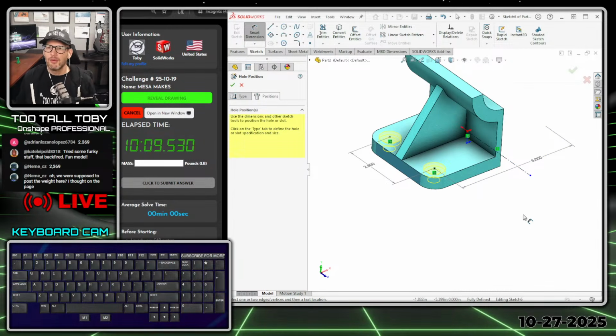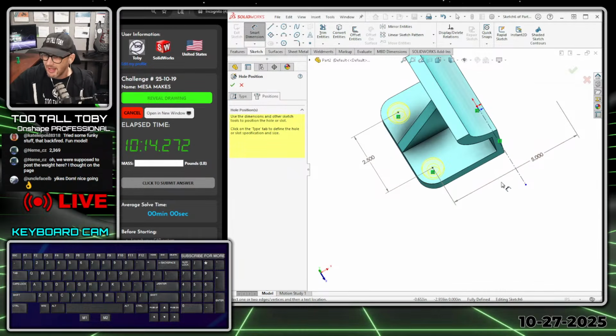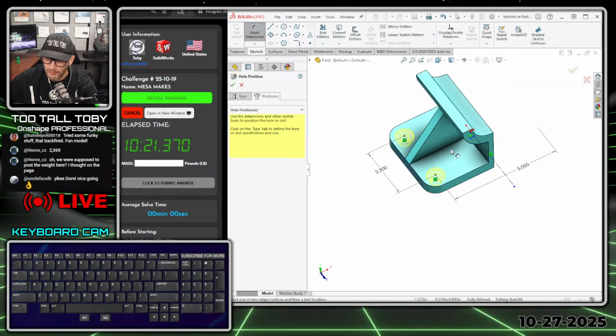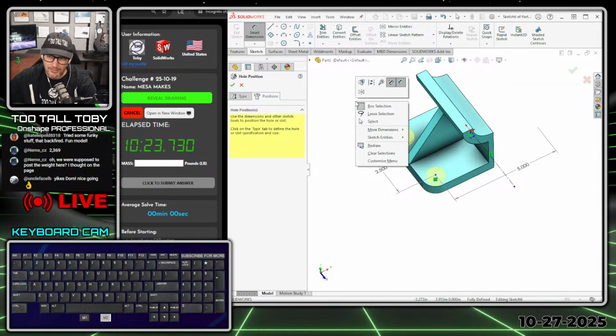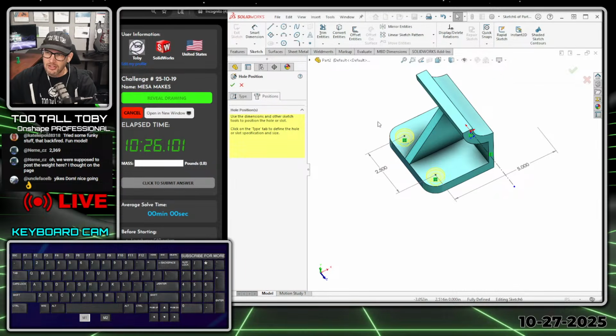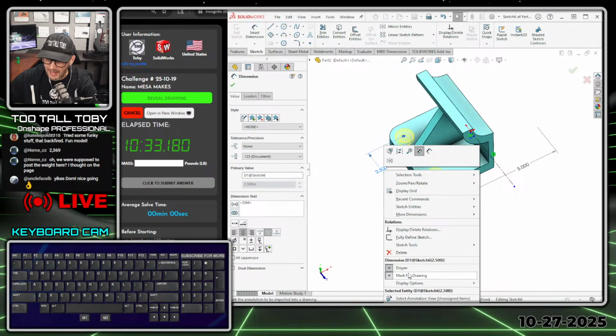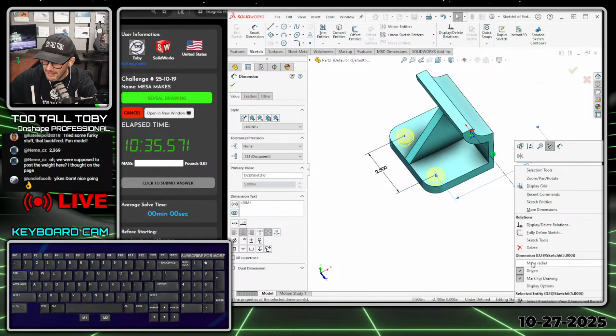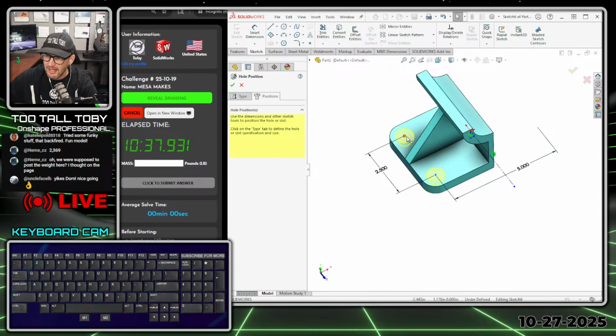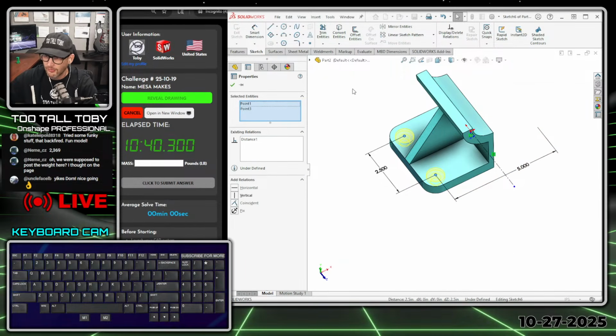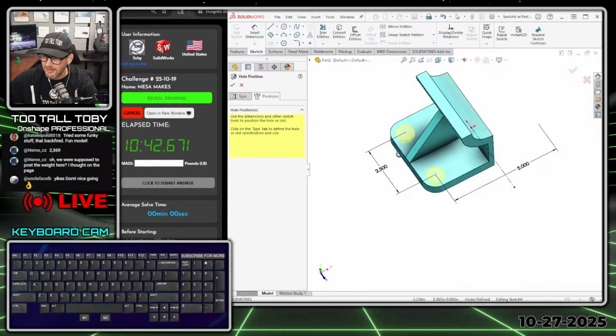Now, I realize that the way that the drawing is dimensioned is as though those are the driving dimensions. But the thing is, you can tell that they're concentric. You can just tell from looking at it that they're concentric. And if you're not sure, add in the driven dimensions, and that'll confirm that those are concentric. Okay, if you don't like that method, if you feel like you should always adhere to the drawing, just select here, click on this dimension, this relationship, delete it, click on this relationship, delete it, click on this dimension, right click on this dimension, make it not driven. Okay, now they're driving, and then take this point, hold control this point, and then you can make those vertical, which I'm going to do with the letter V for vertical.